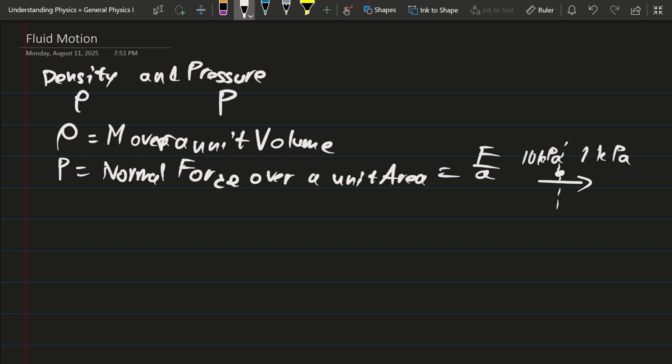The best way for you to understand this is that this 10 kilopascal will be multiplied by the area of the object, which we'll call A, and then if you see the normal vectors here, this side will have 10 times the force compared to the other side. So that means it will experience about 9 times the net force on the object. Basically, that's the main idea.